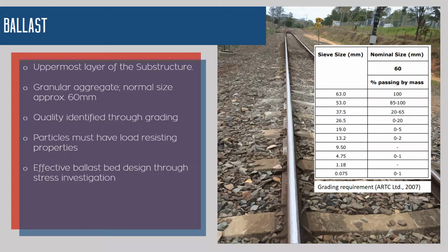To effectively design the ballast bed, it is vital to know the traffic tasks it will encounter. The thickness of the ballast should be determined as a result of the maximum stress at the interfaces, acceptable bearing pressure of the underlying layers, and the stress distribution through the body of the ballast.